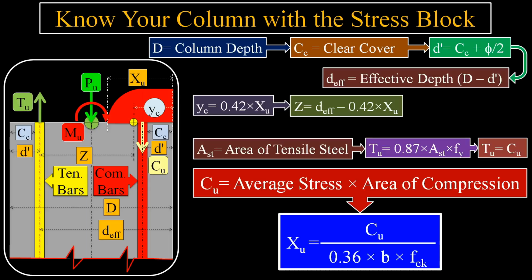Furthermore, when designing a column for moments in both directions, biaxial bending, we must apply these same principles to analyze the second axis. In that analysis, we simply interchange the section dimensions, using D in the formula's width term instead of B. This ensures the section is safe for bending around the Z-axis as well. Now let's move to the next slide, for calculation of strain in concrete and steel.